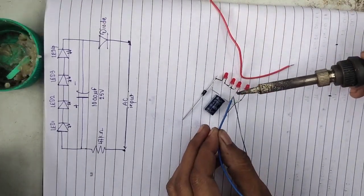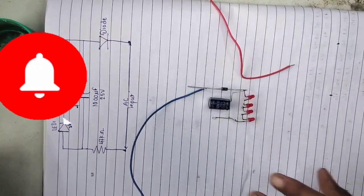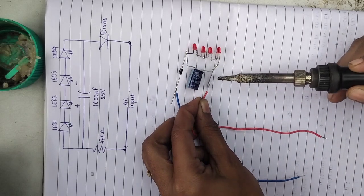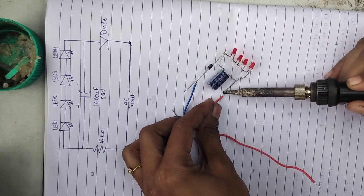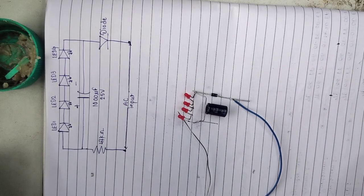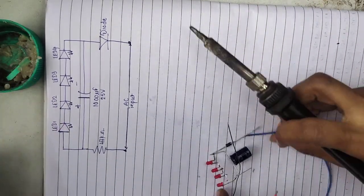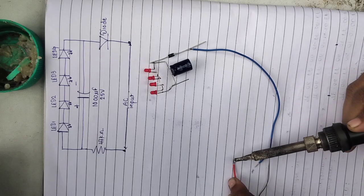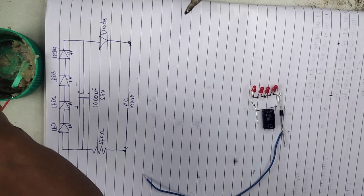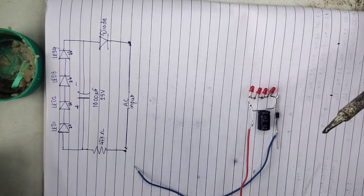Now here we will start the circuit connection as per the circuit diagram. Here I have taken a capacitor of 1000 microfarad as of now, and it's a 25 volt electrolytic capacitor. There is no X-rated capacitor that I'm using here, because we will have the flow of current only for the positive half cycle, because of the diodes we are using. LEDs are also diodes, right? If you don't know about the diode and want to know more, please check the detailed video I have posted on the same.